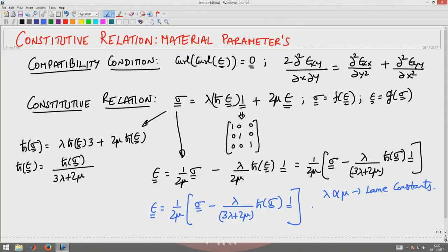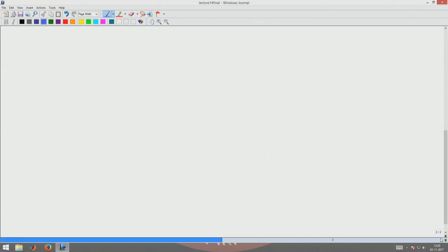It turns out that it is difficult to find these Lamé constants directly from an experiment. So, we will do a uniaxial experiment first, which is a common experiment done on materials to find the material parameters, and relate Young's modulus and Poisson's ratio to the Lamé constants, where Young's modulus and Poisson's ratio are parameters that you obtain from a uniaxial experiment. So, what is this uniaxial experiment?